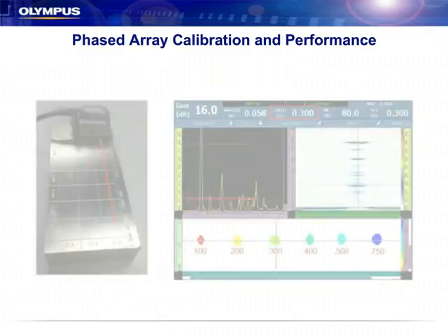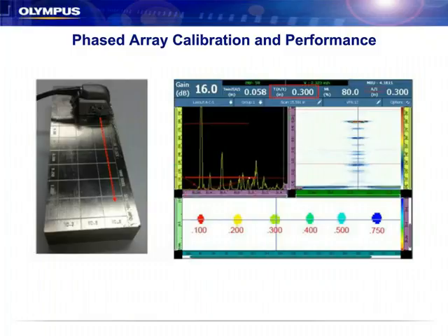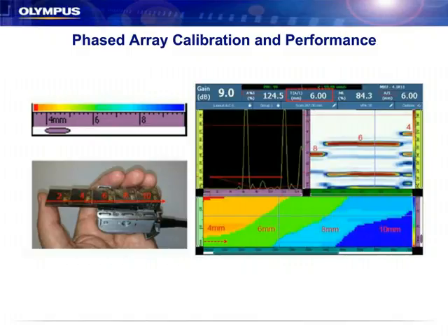Another resolution block here, 0.1 to 750. It gives us good confidence that the system is set up properly and we can get the measurement and depth value precision that we're looking for. There's also a general thickness gauge step that we might use to calibrate a thickness gauge. It's very easy to run that over the DLA probe, and you can show the linearity across the whole thickness scale that you're trying to measure very easily and save that file for auditability purposes.